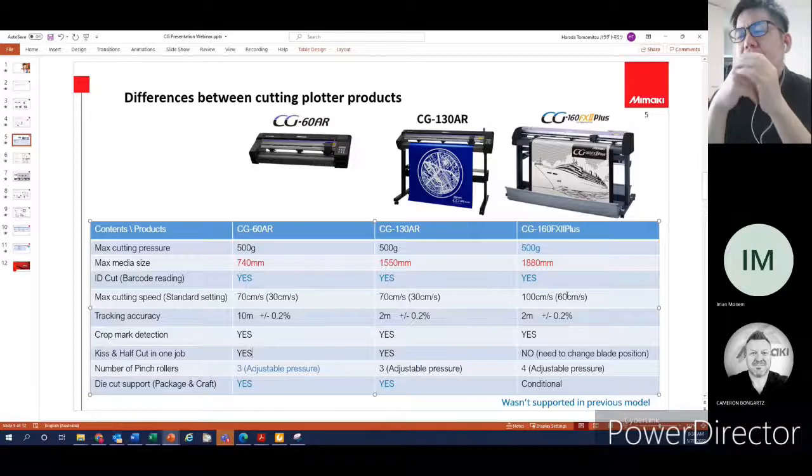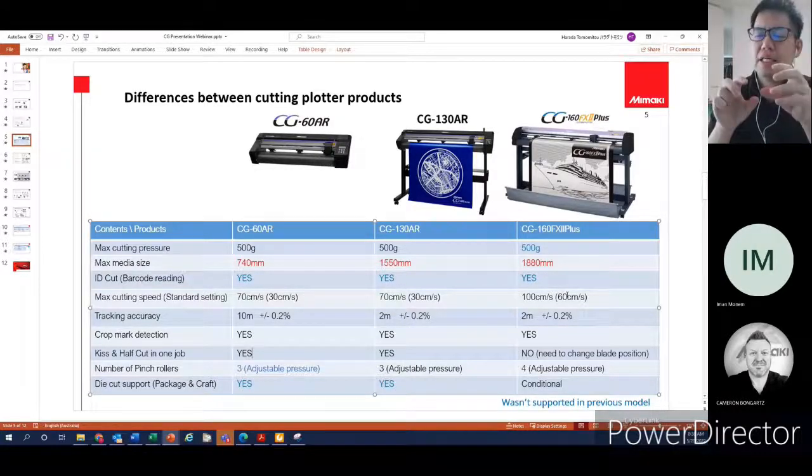I see. Well, I think the problem is that even if you've got 700 or 600 mil of media, you set all the pinch rollers as using 6 or 7 pieces of pinch roller. But you've got only 3 pinch rollers on the media.